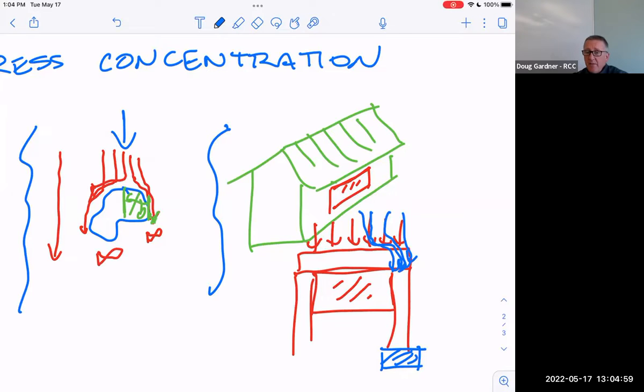In this case, the roof doesn't know there's a window, it just knows there's a beam. But that's what you do for a door or a window. Anytime there's a hole, and I mentioned this window over here, notice that's a gigantic window. It goes all the way across this building. And so there must be a huge beam because it's so huge. And there's no structural support here. This is just a frame for this glass. That's literally like one giant long piece of glass.